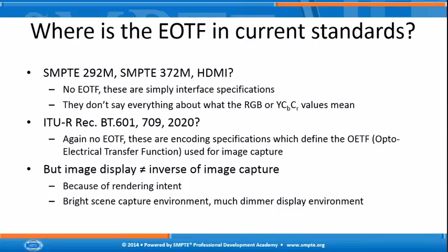They don't say everything about what the RGB and YCbCr values they contain mean. They talk a lot about how to get the bits down pipelines. They talk a lot even about potentially what white point is used or what color primaries are used, but they don't really describe the curve we need to convert those signals back into light at the display device.